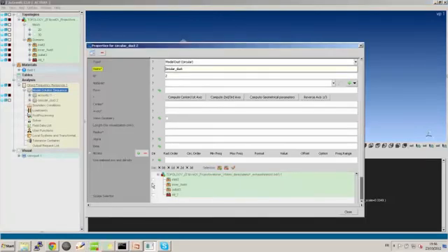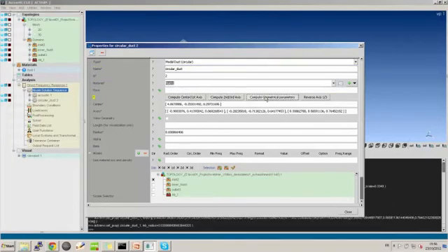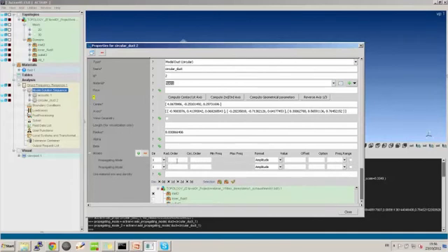Here, what I will do is at first create the inlet. So I am assigning the domain and the material. I'm computing the geometrical parameters and the modal duct system of axes. And I will now create two modes. The first mode is a propagating mode, so it is representing the engine pulse excitation. I will allow all the modes from 0 to 750 Hertz. In this case, it will only be the plane wave.